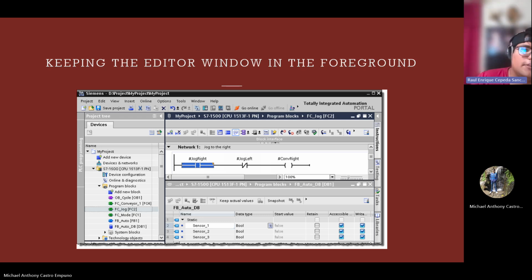Station with configuration. If the station is already configured, then the entire station, central and distributed hardware with parameter assignments, the entire program with comments and symbols is available to the user offline for further processing after the device is loaded. Station without configuration. If the CPU was only assigned an IP address without further configuration, only the actual configuration of the central hardware is available to the user after the load.